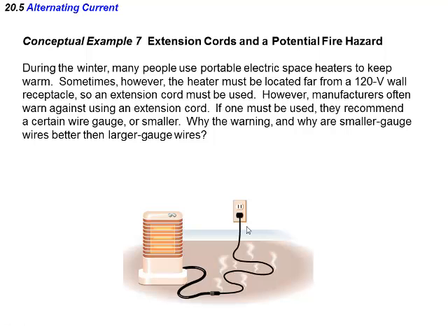This talks about extension cords heating up. That's a good safety thing. The point is, if you have a larger gauge wire, you're going to have a lower resistance, which would decrease your chance of that resistance heating up, because there is a temperature factor with it.